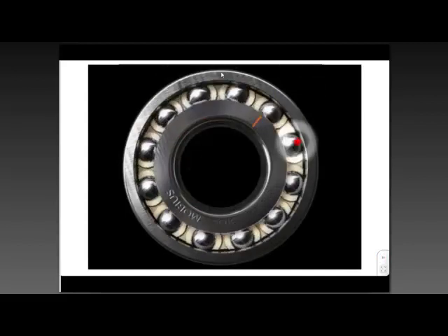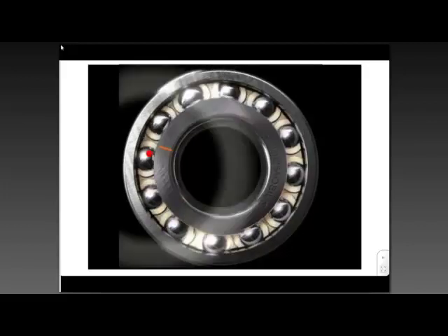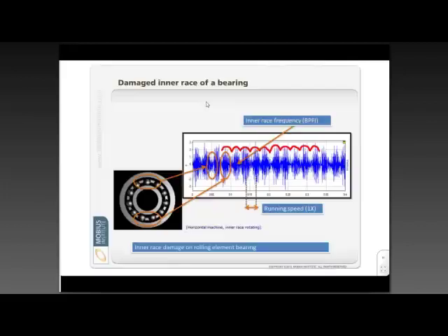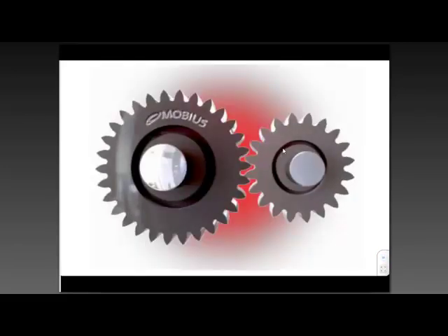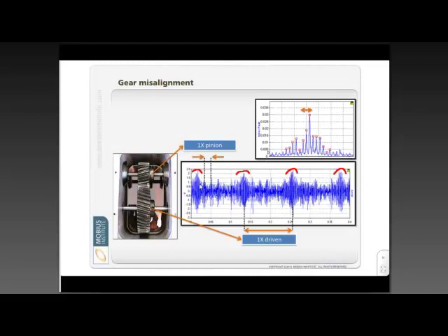If you have a bearing fault, for example, and as that ball rolls along and there's damage on the rolling element, and we look at that from a time waveform point of view, we can see that the time waveform seems to rise up and fall down, rise up. You can see there's lots of little squiggles. It's very complicated, but the fact is that if I look at that time waveform, I get a very good sense of the severity of the problem by how many G's of vibration I'm seeing, and this rise and fall, this pattern you can see here is telling me a lot about the nature of the problem. If, for example, I've got problems with a gearbox, well, here I can see this change.